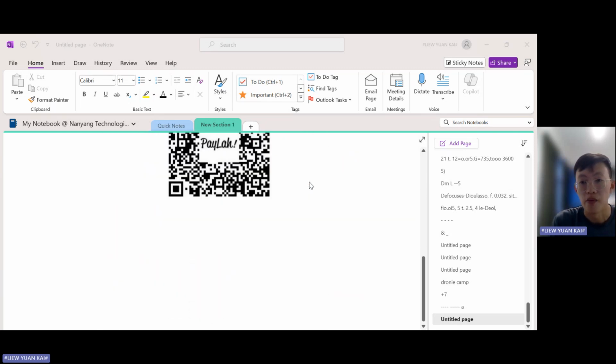Indeterminate structures are where the number of unknown reaction forces exceeds the number of equilibrium equations to solve the reaction forces. Let me say that again. For indeterminate structures, the number of unknown reaction forces is greater than the number of equilibrium equations to solve those unknown reaction forces. Let me start from the beginning. If you have one unknown, you need one equation. Two unknowns, you need two equations. Three unknowns, three equations, right?